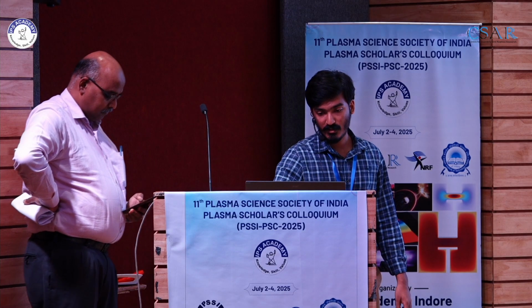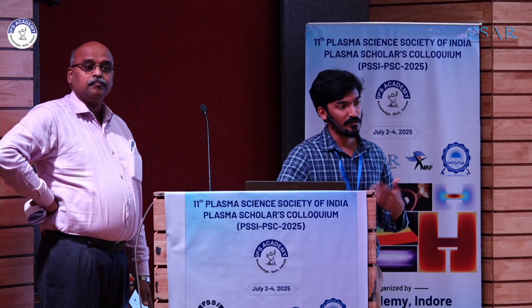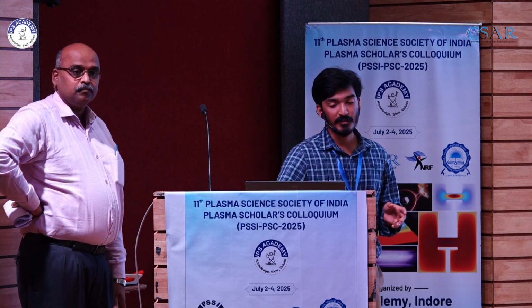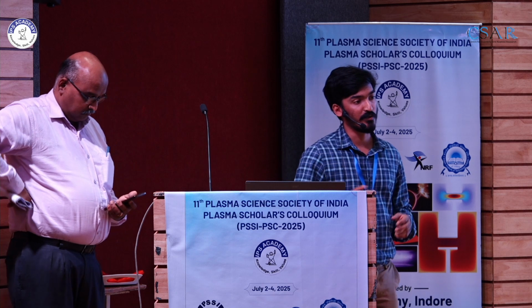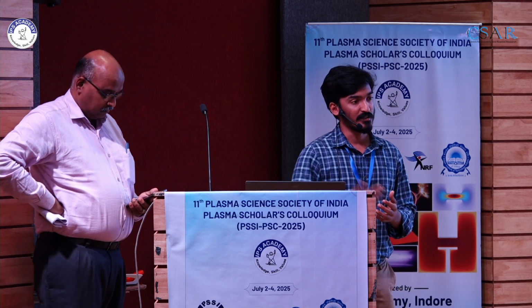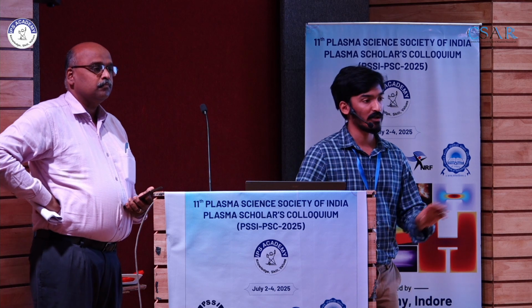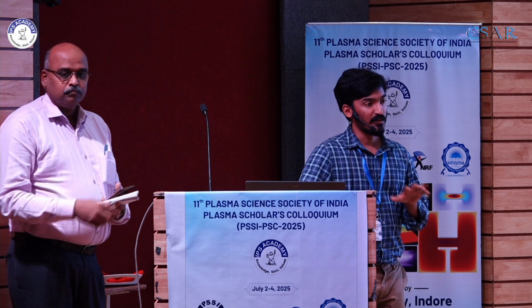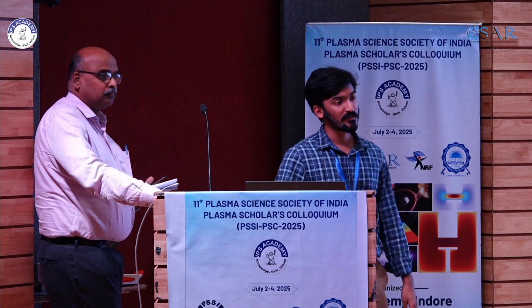Yeah, so in this particular benchmark simulation, they have varied that number, with different particle densities, to verify what is the minimum amount of particles that you require to get statistical accuracy and where the convergence lies. So it was found that starting with 75 ppc, you are more or less at a good compromise between computational load as well as statistical accuracy.